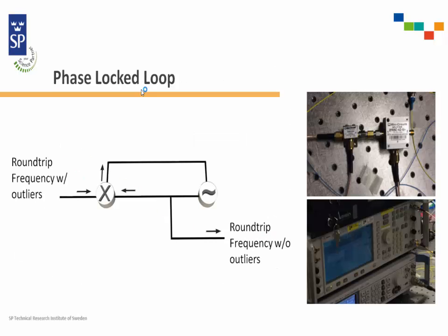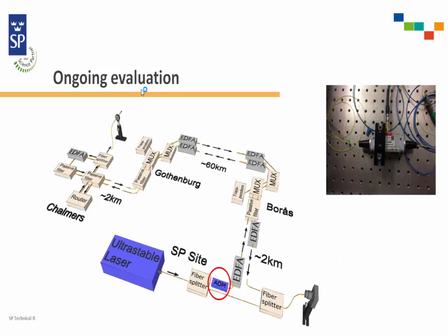But we couldn't settle with that, so we know we have a lot of noise in our connection. So we thought, okay, we need a phase-lock loop. So we created a really simple one, using just the gain of it. We used an ordinary signal generator. We had a mixer. And we introduced it to the system. And since it was already down, we were able to move the acousto-optic modulator to its right place. And up here, we have a picture of it.